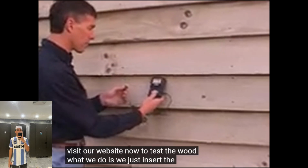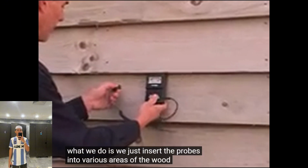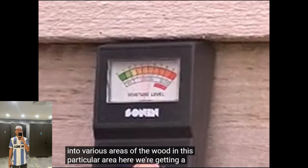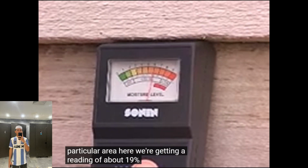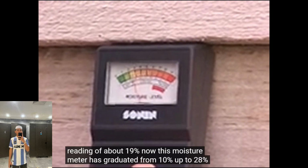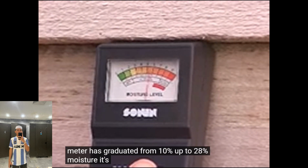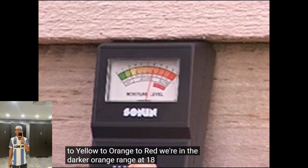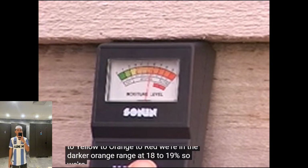We just insert the probes into various areas of the wood. In this particular area, we're getting a reading of about 19% now. This moisture meter is graduated from 10% up to 28% moisture. It's also color coded from green to yellow to orange to red. We're in the darker orange range at 18% to 19%.